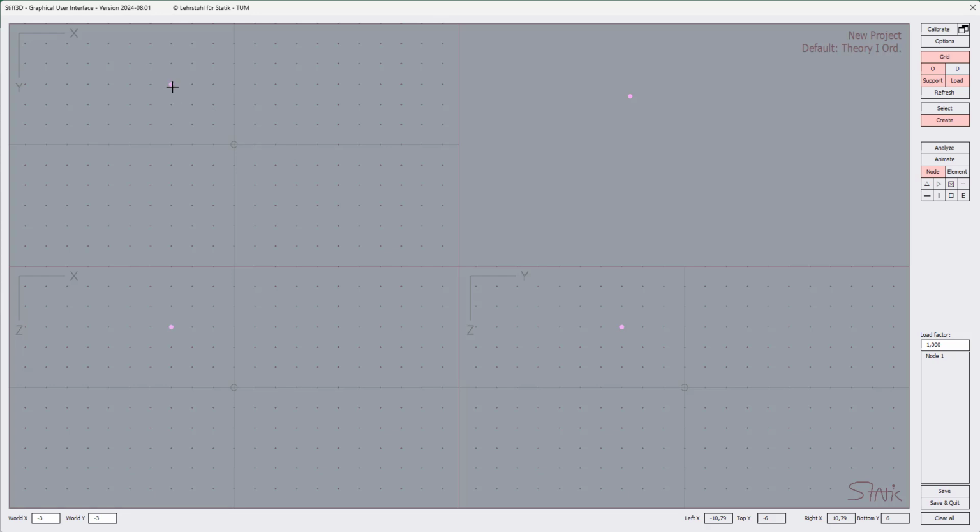Let's now create the node right of that one in X direction, so somewhere there, and again on the top level. We can also go down there just explicitly. I just use the next value for X, should be 3. Pressing the tab key. Now be cautious, we are now here with a Z coordinate. It should also be the top level, it was -3.